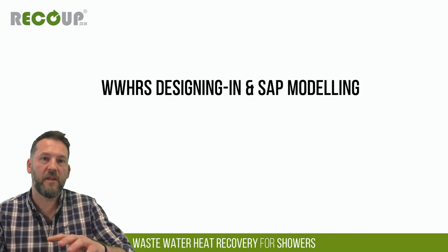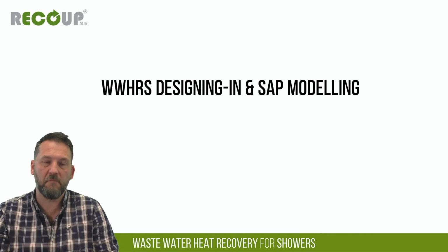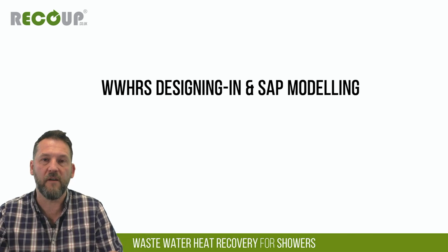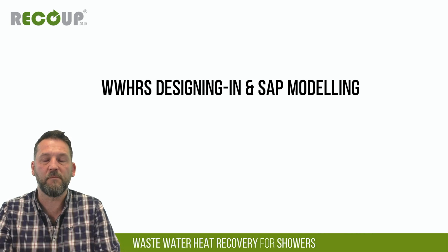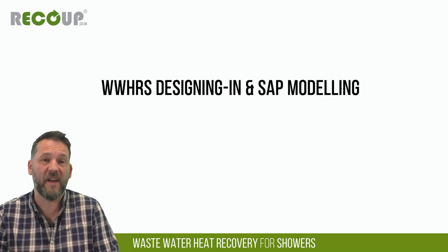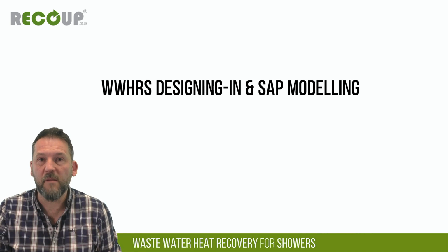So that's why the whole unit is designed so that the cover plate can come off, the percolation plate can come off, and everything is accessible. So periodically, maybe weekly, maybe monthly, maybe quarterly, the unit will need to be pulled apart and cleaned inside and checked that it's free of everything. But that will simply depend on the standard cleaning regime based on the amount of shower traffic there, not really impacted because it's wastewater heat recovery. You would just expect that with linear wet room drains regardless, because obviously they're collecting hair and things, with football boots being banged out into them, that sort of thing.